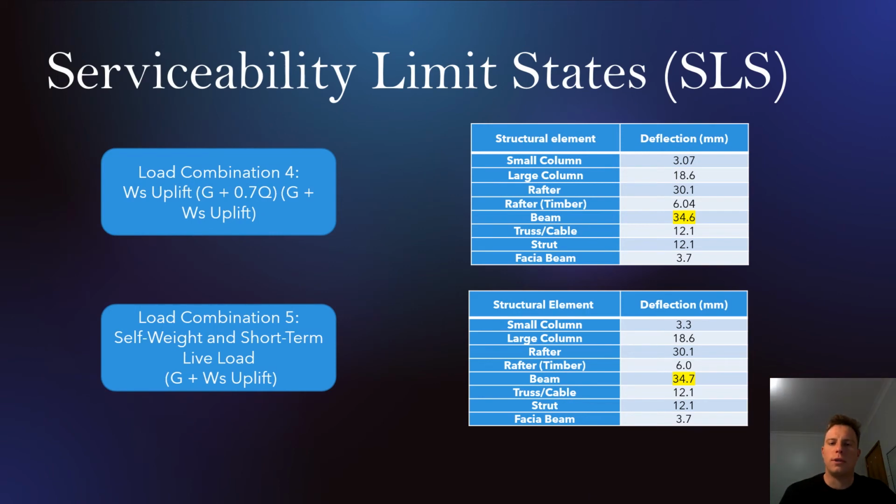Now we move on to the two serviceability limit states. Serviceability limit states are used to reduce deflections in the model. Analysis of this state is important as they correlate to real-world load and pressures that affect the actual walkway structure. The serviceability state, unlike the ultimate limit state, is not confined by failure stresses and is focused on the deflection of members within the structure.